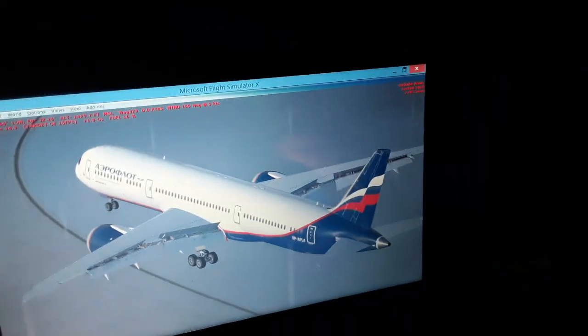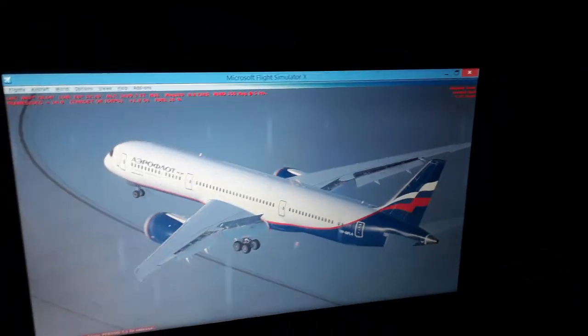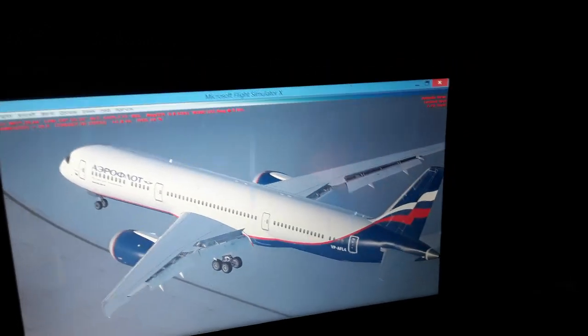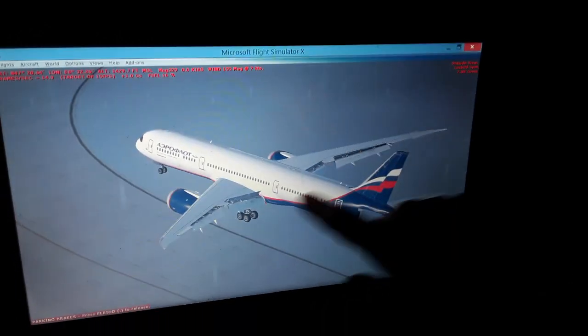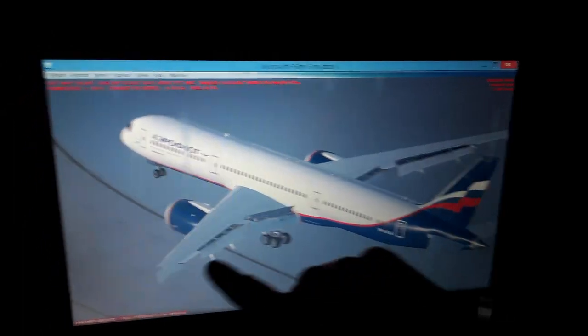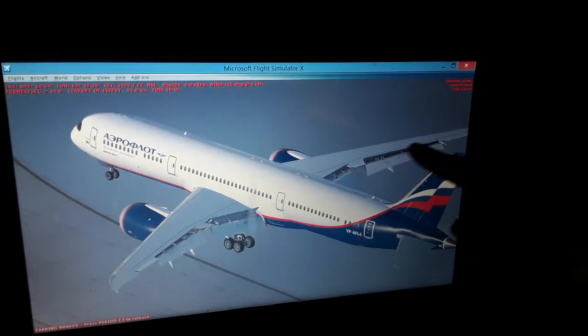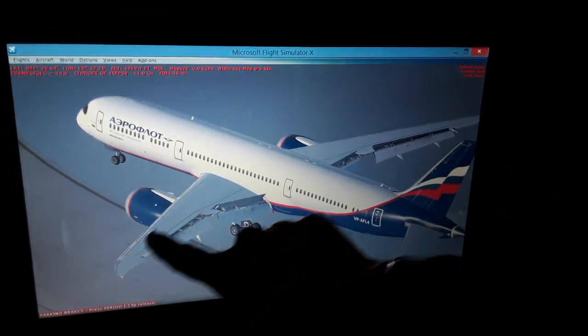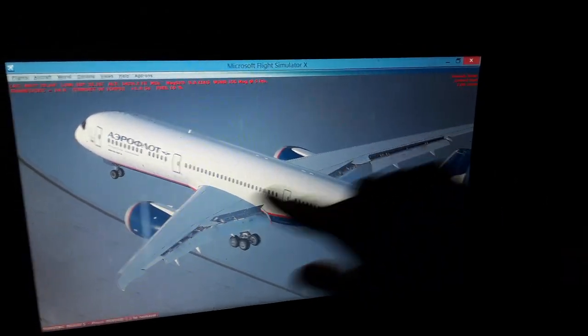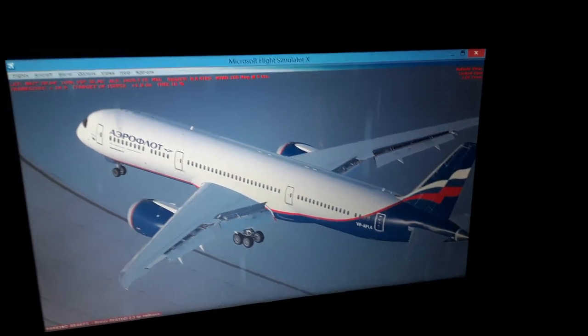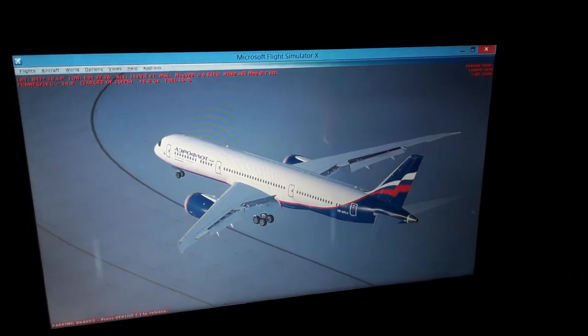You can see here I'm going to talk to you about Newton's physics, aerodynamics, and aerospace engineering. You can see the wings of the aircraft hold the weight of the aircraft as it flies. The mean aerodynamic chord position is at 23% of the MAC, pretty much located here. It is where the maximum aerodynamic lift occurs in the wings. It is also where the stall will begin, as on the top surface of the wings the airflow becomes detached.